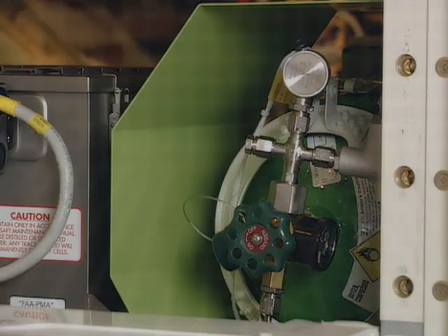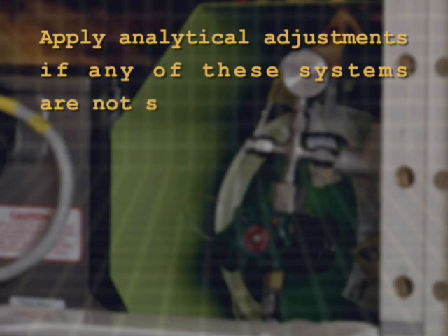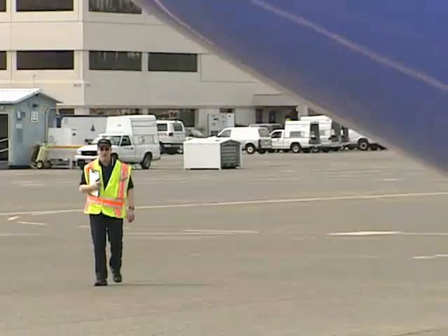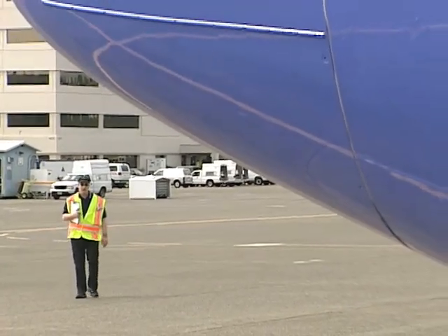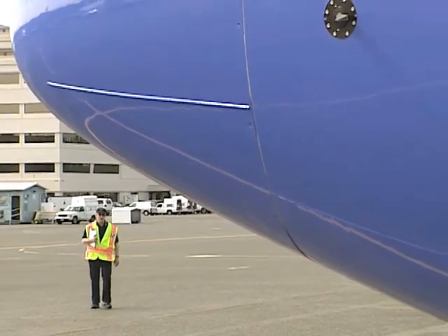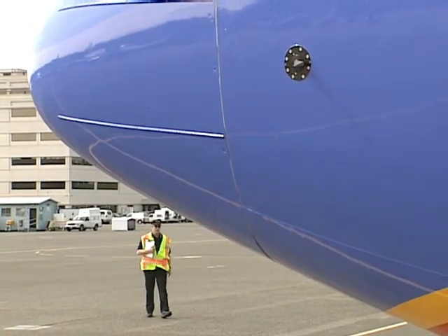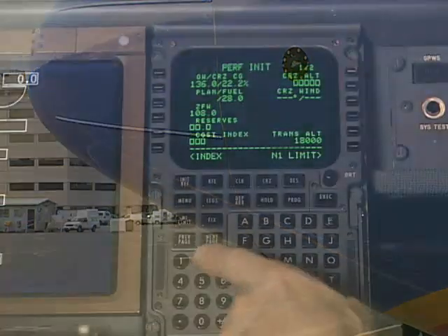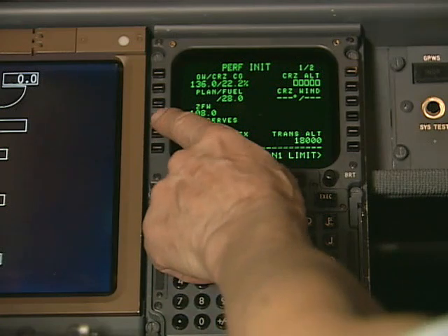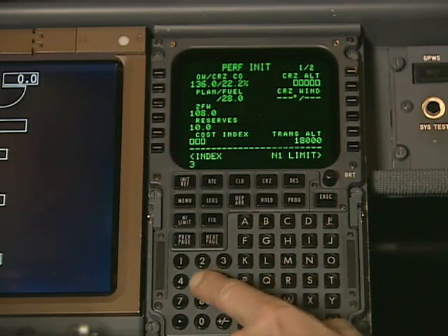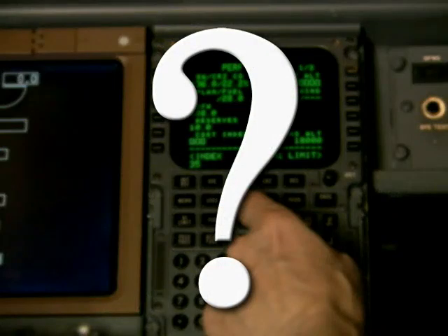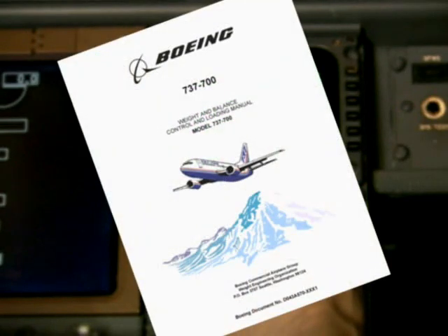Next, we need to conduct an airplane inventory. The problems with getting an accurate basic empty weight often come from errors in this part of the process. So let us take a moment to understand why an accurate inventory is important. As mentioned, in order to predict an airplane's actual weight during operation, you must start with the airplane's basic empty weight. But how do you know what is and what is not included in the basic empty weight? That's where the inventory list comes in and must be created. It defines the contents of the airplane in its basic empty weight configuration.